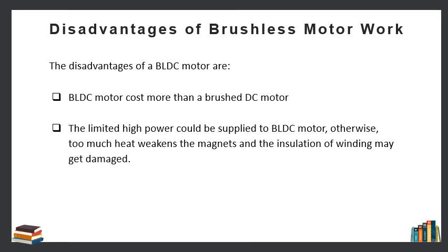Some disadvantages of brushless motors are that a brushless DC motor costs more than a brushed DC motor. Only limited high power can be supplied to a brushless DC motor, otherwise too much heat weakens the magnet and the insulation of the winding may get damaged.